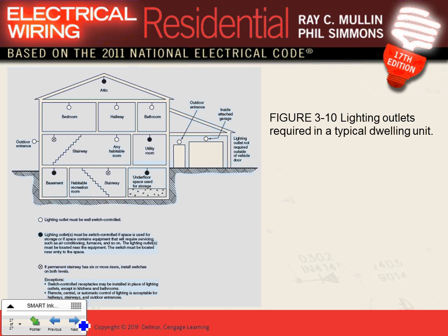Okay, any comments, guys? Any questions before we go into the last one, which talks about lights? Any questions about laying out receptacles? How many receptacles in the bathroom? One receptacle. If there's a requirement for the bathroom receptacle, you have to put it within what? Within 3 feet of the sink.